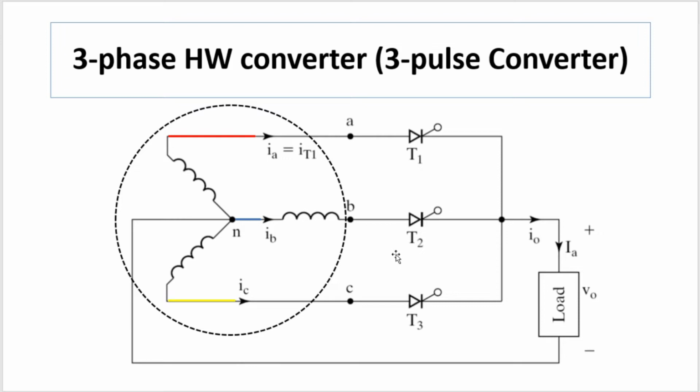The other circuit required in this kind of setup is of course a gate triggering circuit, because we are going to use thyristors as a controlled rectifier. So proper control of its on and off operation will be with the help of these firing pulses, which will be applied on the gate of these thyristors. But ultimately we'll have to design some kind of symmetrical switching whenever we operate these thyristors simultaneously or sequentially. So here we'll start.